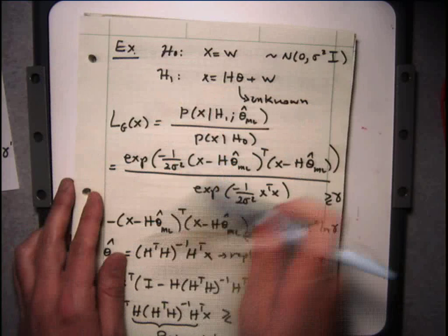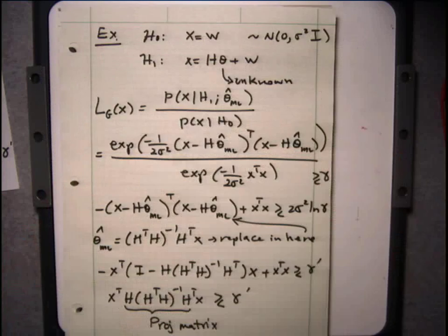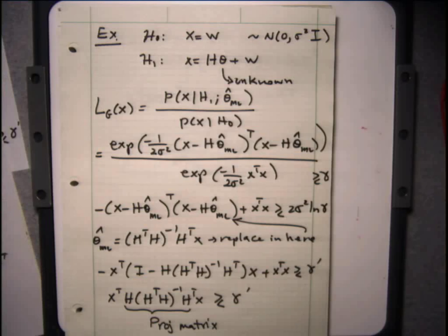So remember what we said. This is basically telling you something about the signal. You know that it lives in this particular space, but that's all you know. You don't know which particular signal it is. So what the detector says is, okay, since I know the signal lives in this space, I'm going to take your measurement, put it in that space, and compare its energy to a threshold. If the signal is present, that threshold should be exceeded. The projection ought to be large.